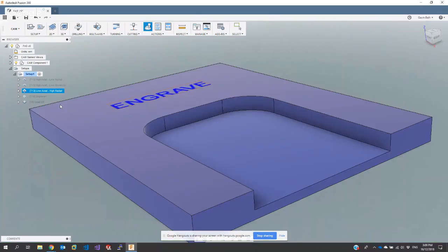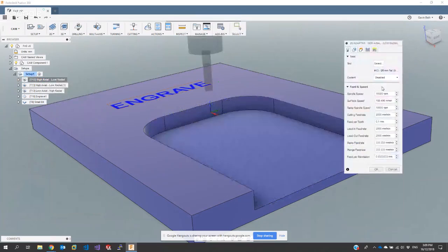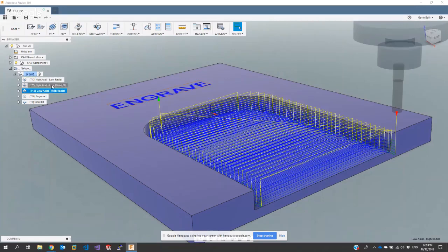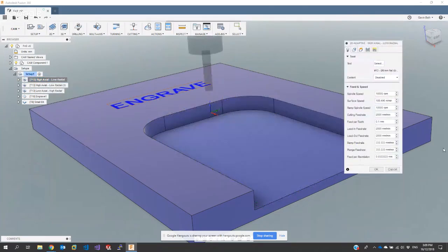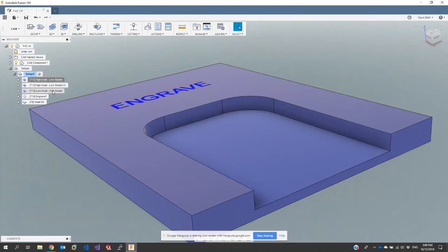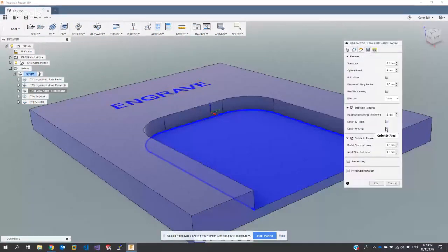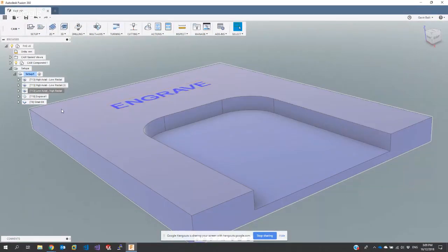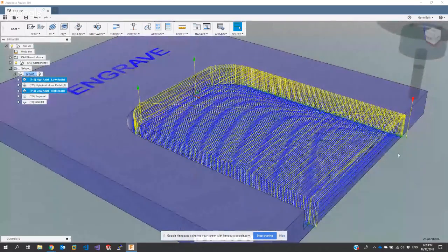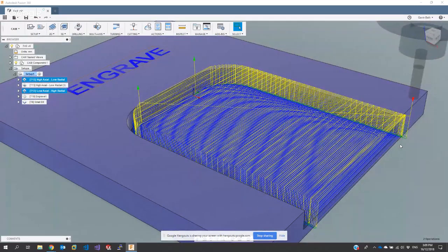14:33. So I've just realized that's not a fair test because one's using both ways adaptive. So I'll just go and turn the both ways off. Where was it? 10,000, 2,000. Sorry, bear with me. Oh, well, anyway. So you can see the comparison in time there between 9 and 14 minutes. Obviously, in that example, the high axial, low radial would be faster.